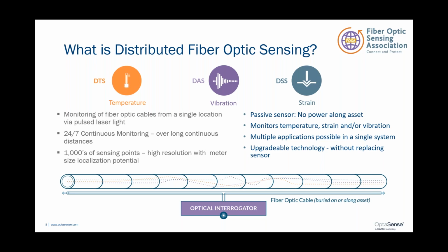In our case, we're using the Rayleigh backscatter, or distributed acoustic sensing as it is commonly known. And what this enables us to do is, from a single location, look both upstream and downstream down the pipeline and turn that piece of glass into a very precise sensor of the acoustic field. And this gives us thousands of sensing points. It's truly a distributed technology.